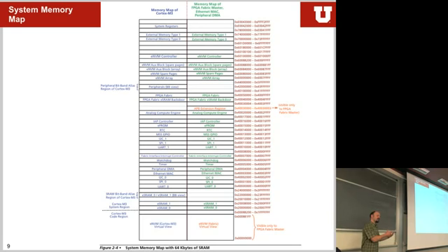So imagine you have a register in the background that toggles your I/O lines, right? So we have a 32-bit register with a lot of slots in here. Assume you can read and write this register. If you read it, you get the status of an I/O line.